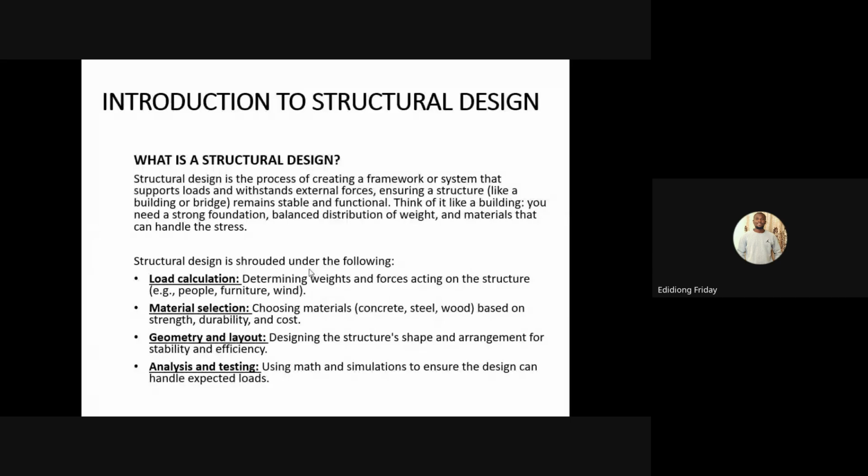I usually tell people that whenever you are doing a structural design, make sure to add all the possible weights, all the possible loads that will be coming on that structure, whether it's a live load, a dead load, or whatever load you perceive will be coming on that structural member. If those load calculations are not done properly, you will end up under designing or over designing, which will lead to structural failure. We're going to see that structural failure later in today's class.